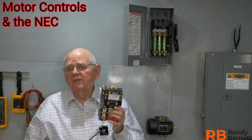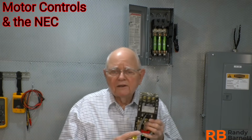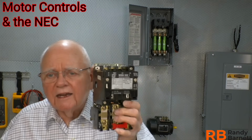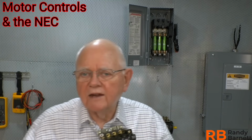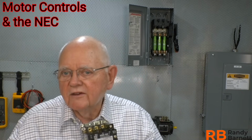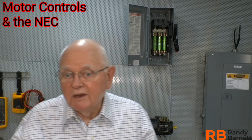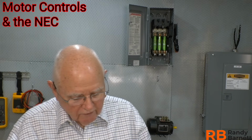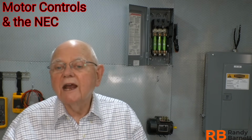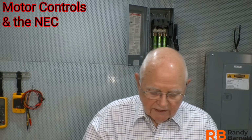NEMA, the National Electrical Manufacturers Association, takes a lot of the guesswork out of this circuit for me. They tell me on the label, if I take a look at it, that it's a NEMA size 1 motor starting contactor. For the NEMA size 1, I can look it up, or it tells me right on the faceplate as well. For a 208/230 volt AC motor, it's rated for 7.5 horsepower. For a 460 or 575 volt AC circuit, it's rated for 10 horsepower.